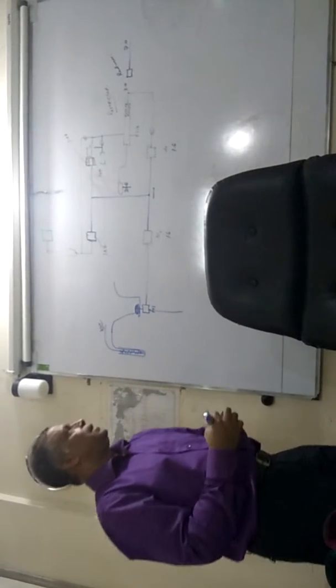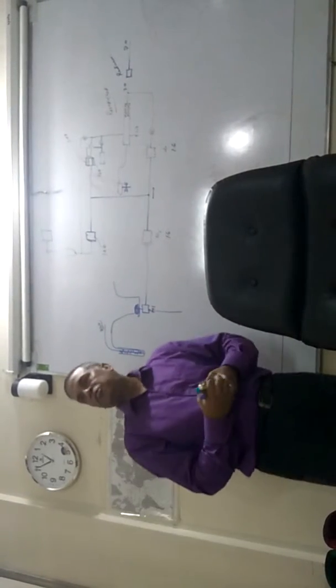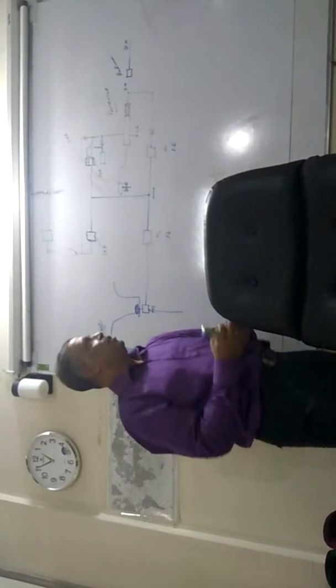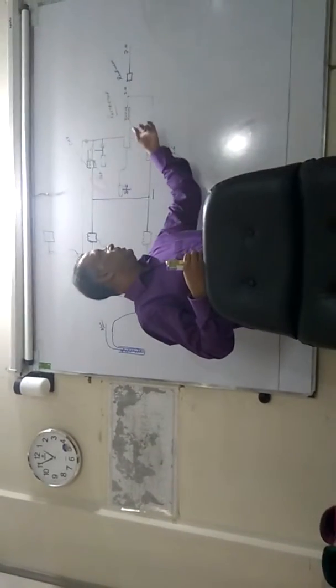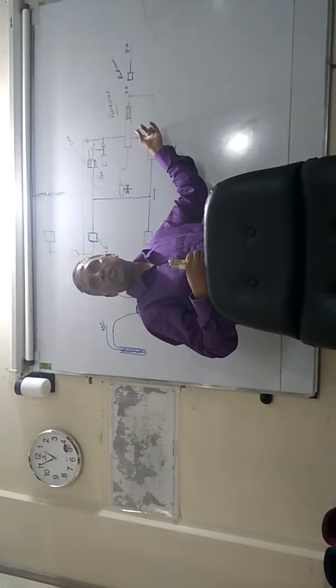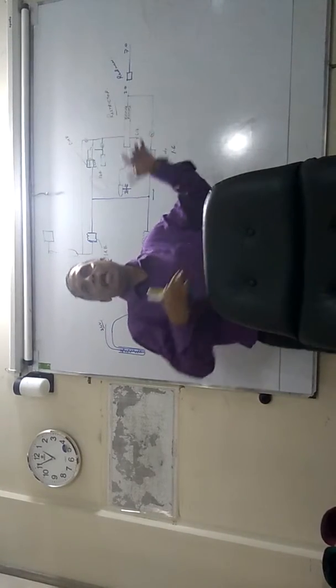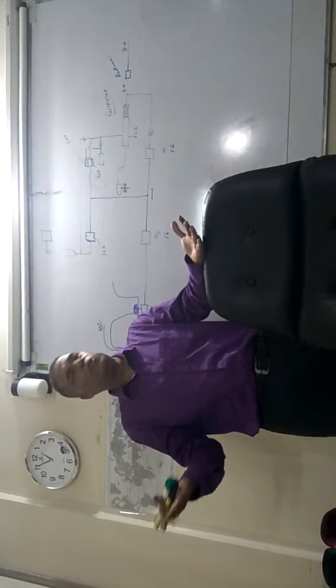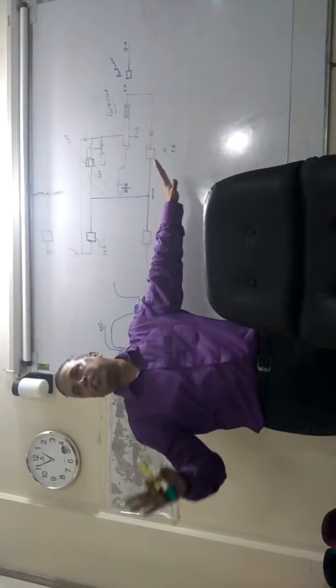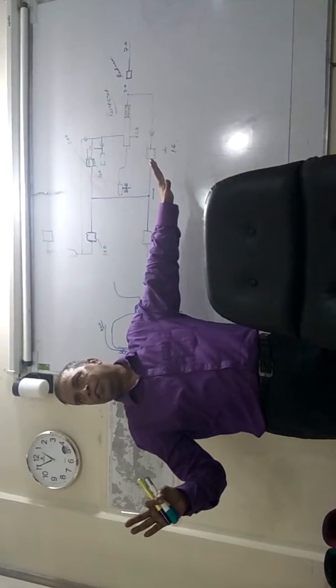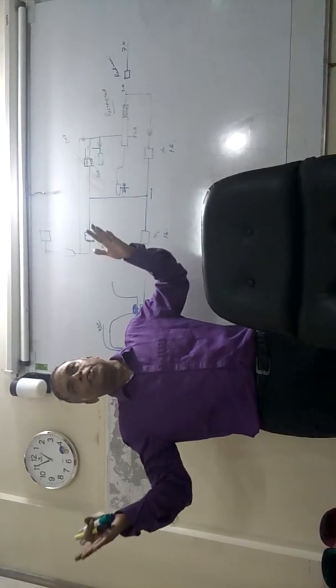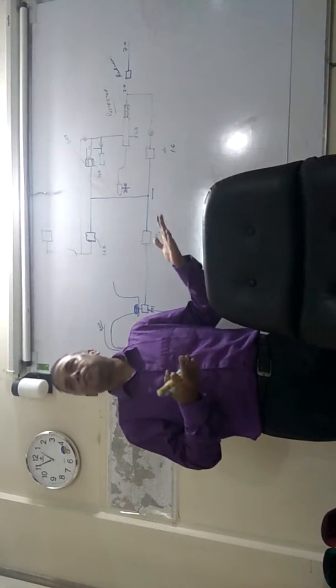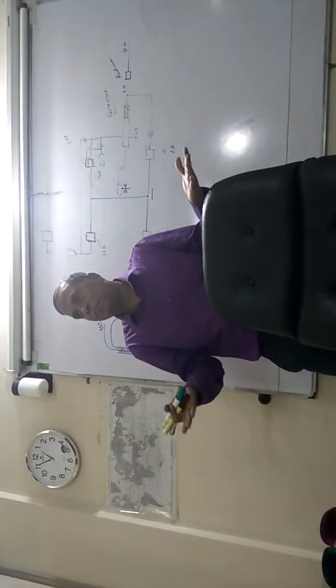So, there is this thing about the controller. Whenever there is a deviation, there is a change in the corrective action pressure. And the ultimate result? The ultimate result is to remove the deviation. Understand? So, measured value and desired value again will be the same.